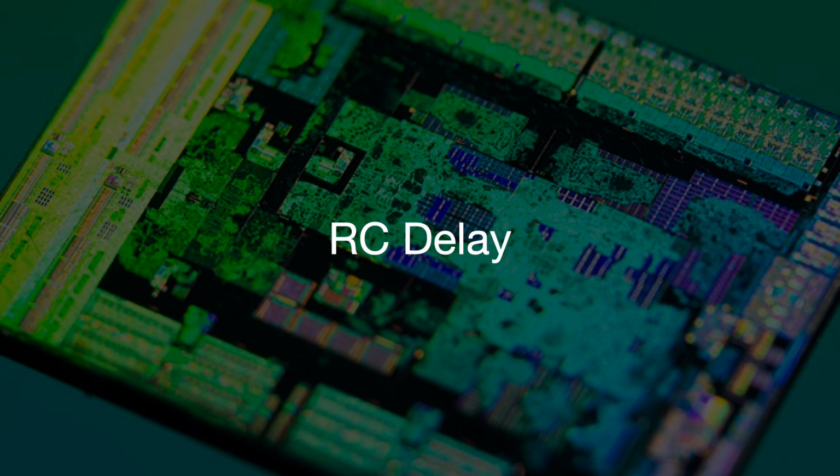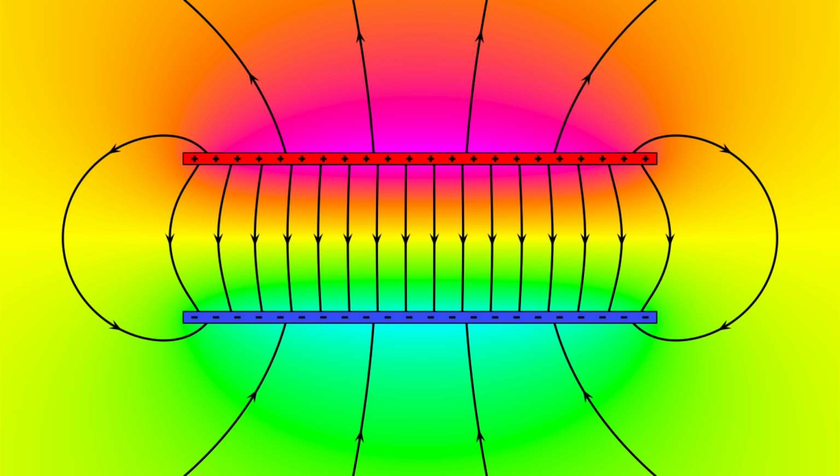Capacitance depends on the dielectric material surrounding the wire. That material has a dielectric constant called K value. It has little to do with superconductors. So even if we cut the line resistance to zero, we still have to deal with the capacitance part of the delay equation. I wonder if the speed gains will be as significant as I initially thought.